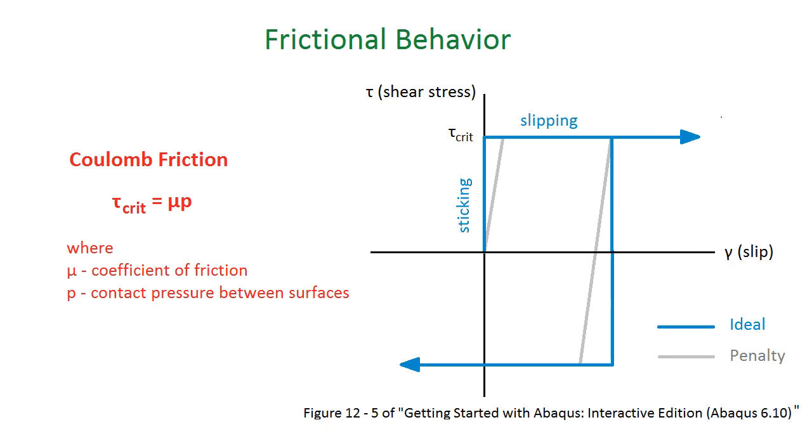In this friction model, the static friction coefficient decays exponentially to the kinetic value. Test data can also be entered to fit the exponential model. In addition, you have the option to specify elastic slip. If you wish to enforce ideal frictional behavior, go with Lagrange multiplier.